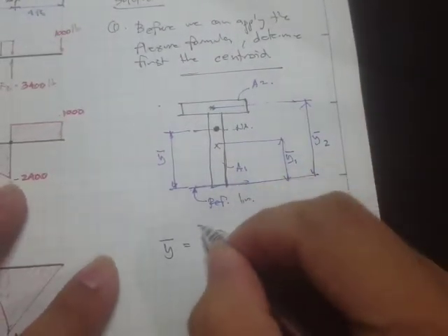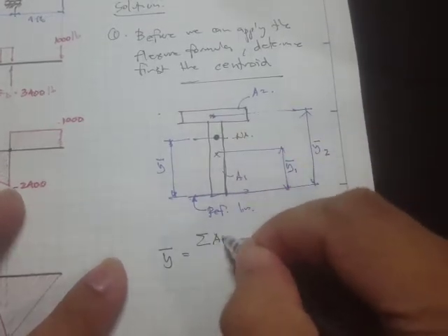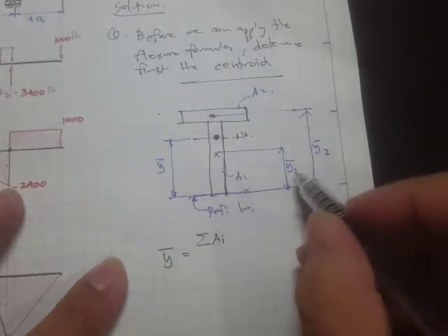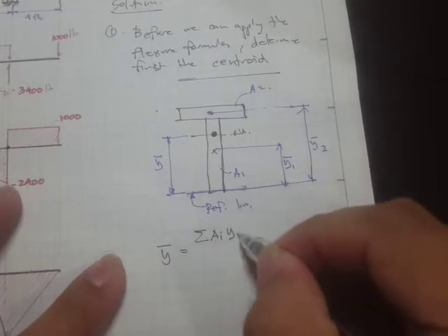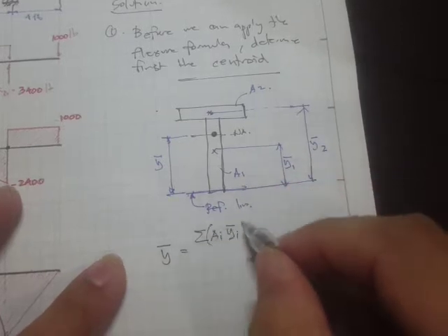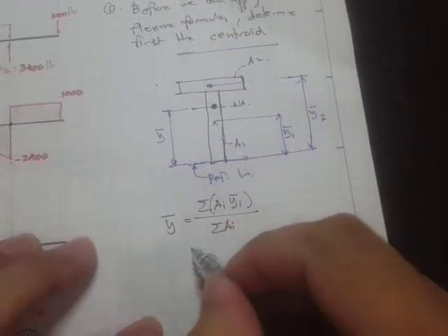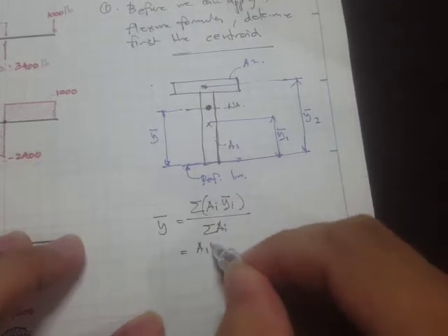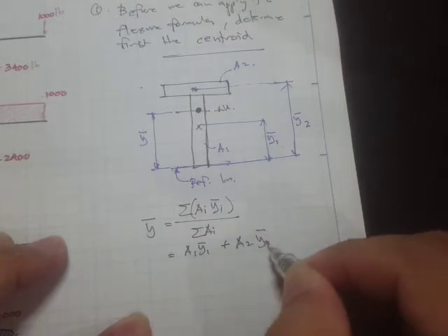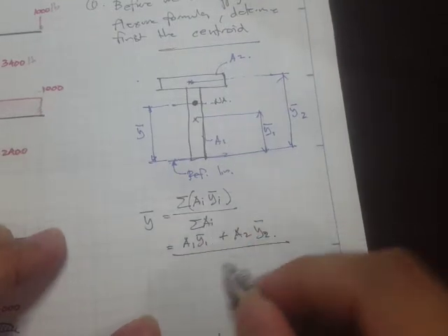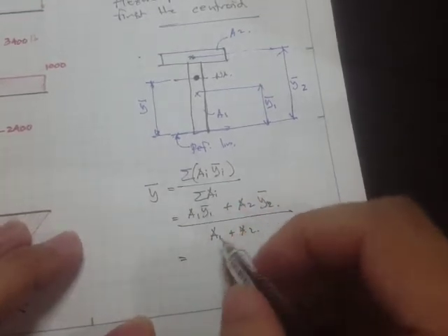So it's just simply the summation of, since we have composite shapes, then that's just going to be AI. So that means we have A1 and A2, the summation of A1 and A2, actually the product, divided by the summation of the AI alone. That simply means we have A1 y bar 1 plus A2 y bar sub 2 all over the summation of area, which is A1 plus A2. And if you substitute all the values, we have